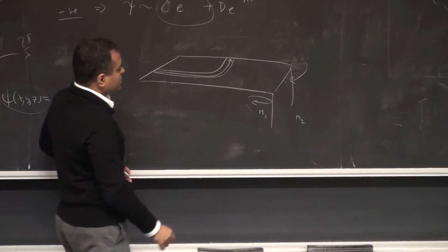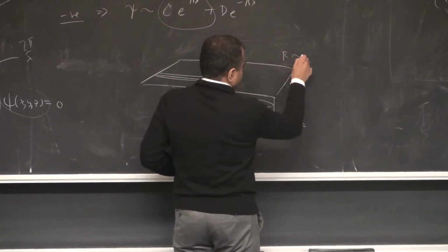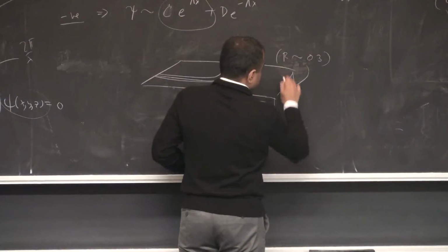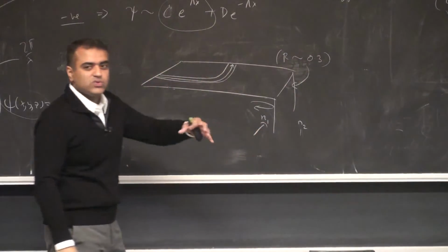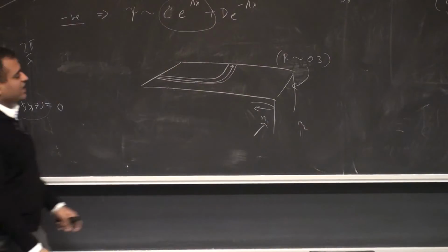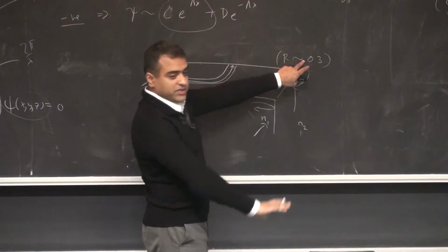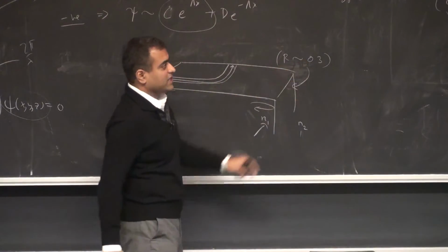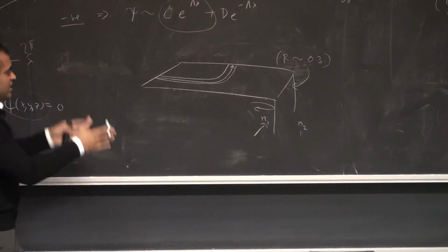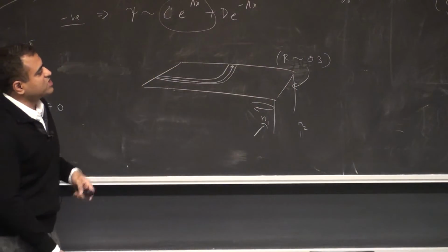But I think you also know that for a semiconductor, the maximum reflectivity you can get out of here is roughly 30%, because the refractive indices are typically of the order 2 to 3, and air is 1, so you get ((N1 minus N2) by (N1 plus N2)) squared, a reflectivity of roughly 30%. But that's an etched facet mirror, and you can actually do much better.